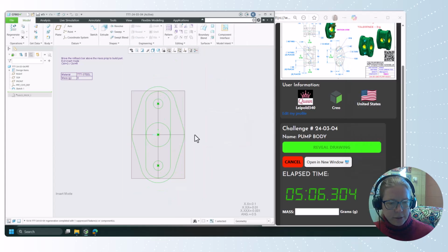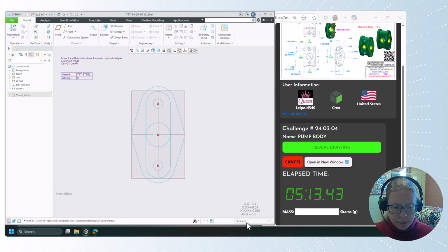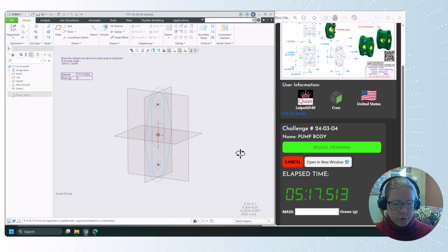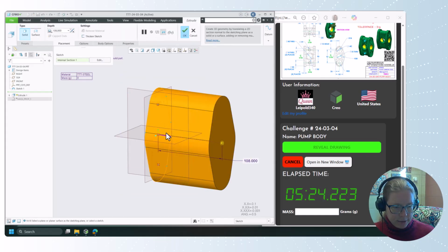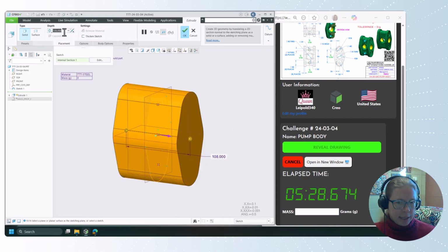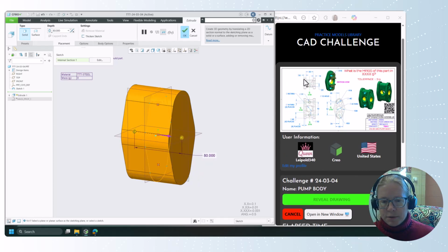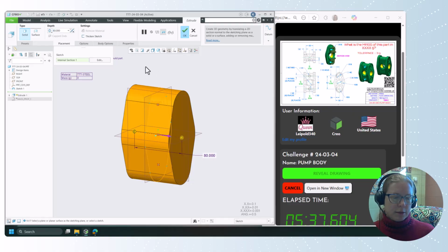And you know what? Let's go ahead and get that. Nope. Yep. Yeah. So we're going to use sketch regions. And we're going to start by extruding kind of everything. Let's get everything. We're going to extrude the whole thing symmetric with a 50 plus 15 plus 15. So that comes from the top view. We have an overall width of 80.